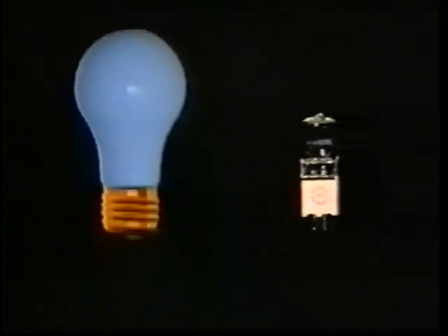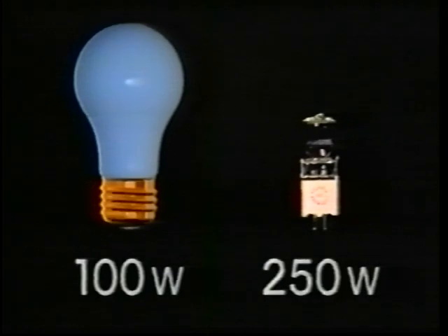And thanks to the lamp's design and operating principles, there are some additional benefits. First, there's the small size in relation to the wattage. A tungsten halogen lamp requires a much smaller envelope than a normal incandescent lamp. This smaller envelope is also useful because it helps keep the lamp temperature up. That's important since the halogen cycle requires the temperature of the bulb wall to be at least 250 degrees centigrade.